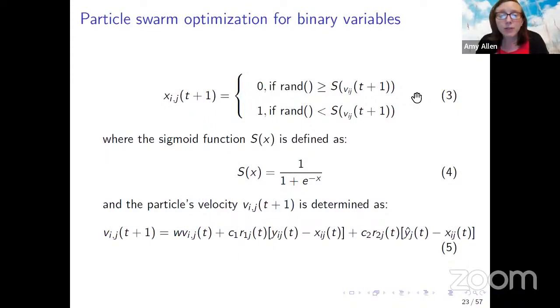With the minimal spanning tree heuristic validated, I turned my attention to the aspect of the problem of selecting the optimal subset of buildings to be connected to the district energy system. And I sought to address this with particle swarm optimization, or PSO, which is a meta-heuristic approach in which elements of a swarm of animals that could exist in the natural world can be conceptualized as evaluating candidate solutions in the search space, which they move through at some velocity.